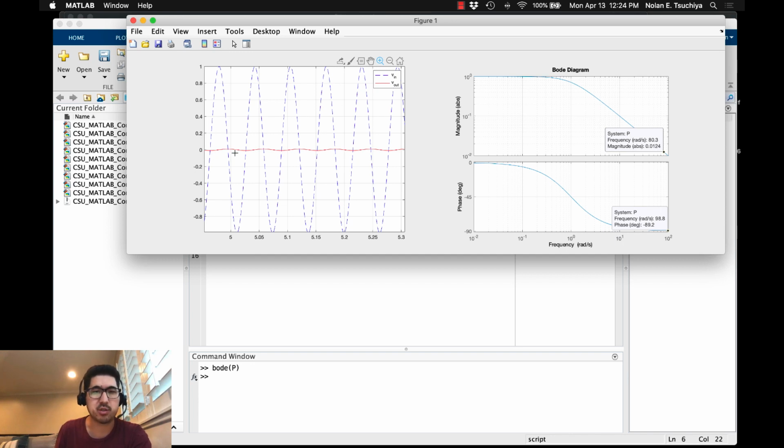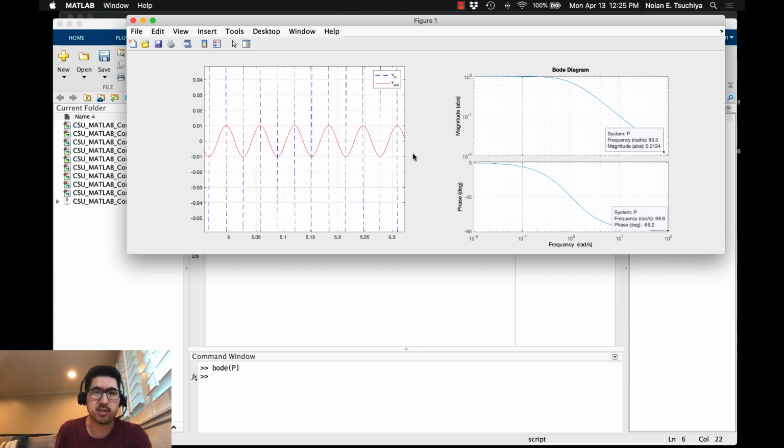The red plot is actually a sinusoidal function, oscillating up and down. Furthermore, it's out of phase by a lot more than just negative 5 degrees. We're at negative 90 degrees lagging behind the input, which basically means every time we hit a peak on the input, we should be passing through 0 on the output, and vice versa, which is precisely what we're seeing here. If I zoom in even more on just the output side, of course the scale is going to change, and we can see that we have an amplitude of about 0.01, which is highly attenuated compared to the input.